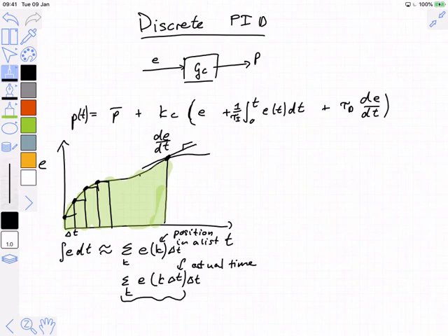So we'll just be accumulating the most recent error value into a running total, just from an implementation point of view. It's usually quite inefficient to remember the entire history. If you think about a little controller box that we're building, a box that's supposed to be plugged in and forgotten about, it's unlikely that that box will have an indefinite memory that can store all of the values it has ever seen.